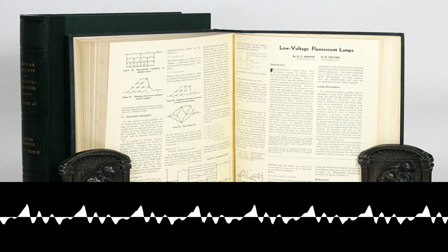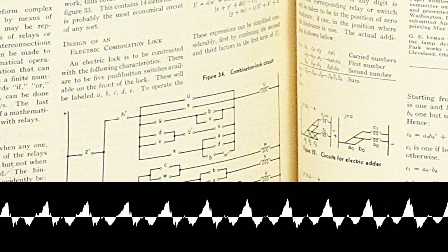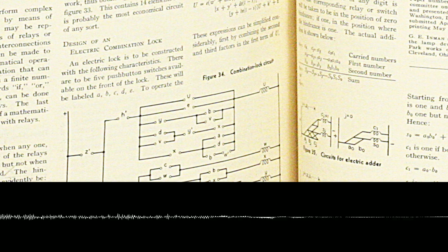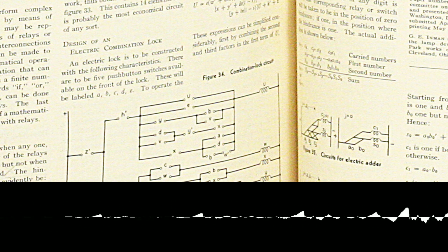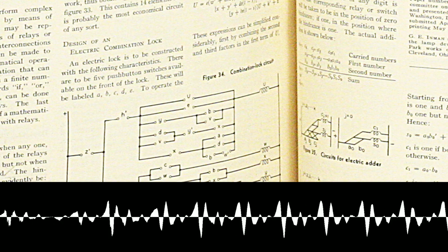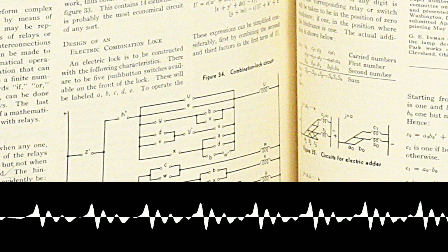Section 2: Algebraic Representation of Relay Circuits. The cornerstone of Shannon's approach resides in his formulation of the algebraic representation of relay circuits. He begins by establishing a correspondence between the Boolean values of 0 and 1 and the open and closed states of a switch, respectively. A switch is closed when current passes through it, otherwise it is open. These states are explicitly represented by variables.